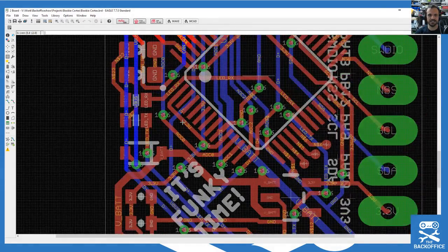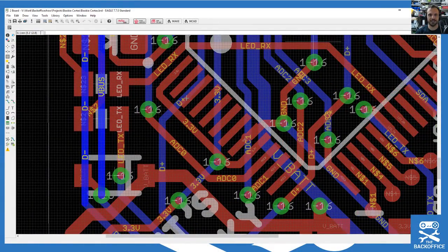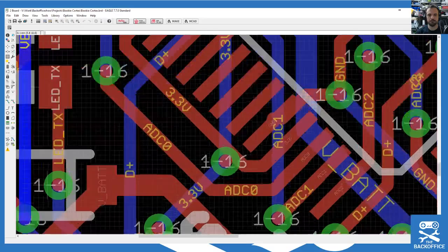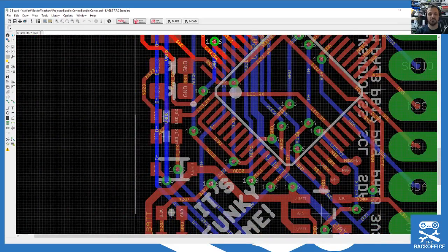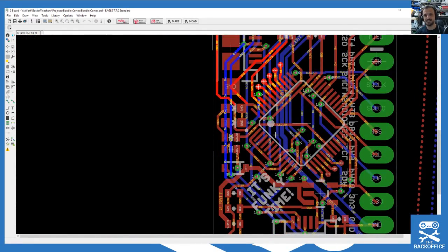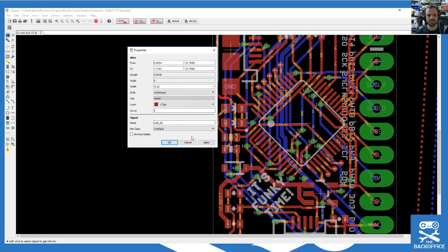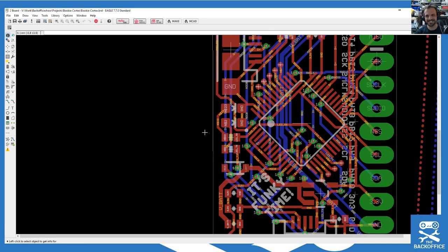You can see it's a pretty dense design, so there's not much scope for bringing out some of these other pins. But I just brought out what I could. So even if you want to experiment, if you're like me, you can get down there with your little bit of Kynar and touch it off a test pin. You will at least be able to, for experimental purposes, get some additional I/O if you need some.